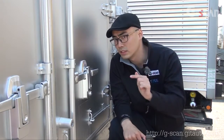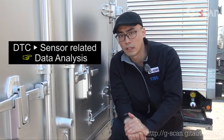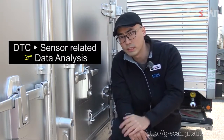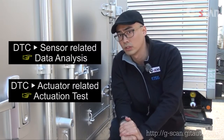Do not just assume the component related to the DTC is defective, because there might be other problems which cause the ECU to trigger the DTC. When the DTC is sensor related, go to data analysis and check suspect parts data. When the DTC is actuator related, perform the actuation test and check the suspect part for its operation. When you diagnose commercial trucks using useful functions of G Scan, I'm sure you will save a lot of time.